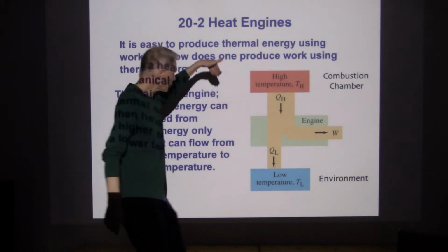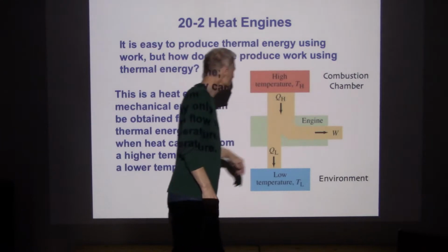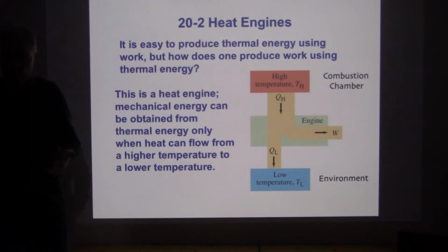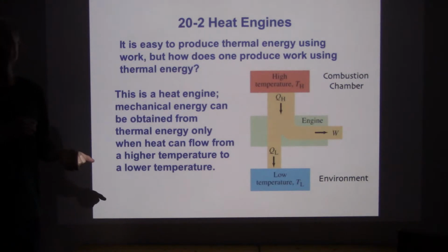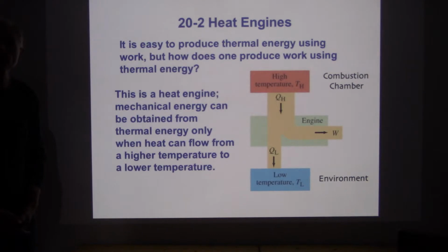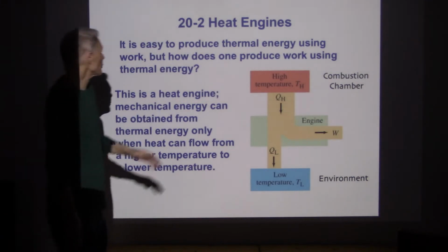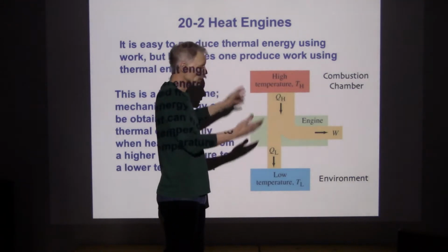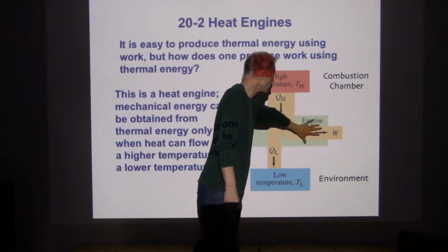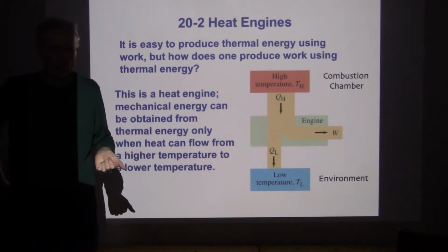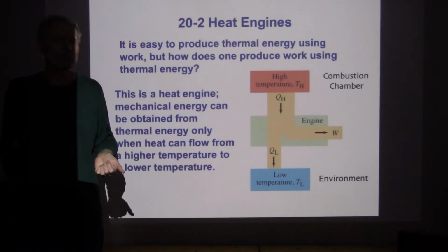Now, we're going to divert some of this energy to the engine, and so we would like to convert as much of this heat as we can into work. If possible, for every 100 joules of heat we generate, it'd be great to get 100 joules of work coming out. Turns out that most heat engines are no more than 20 or 30% efficient.